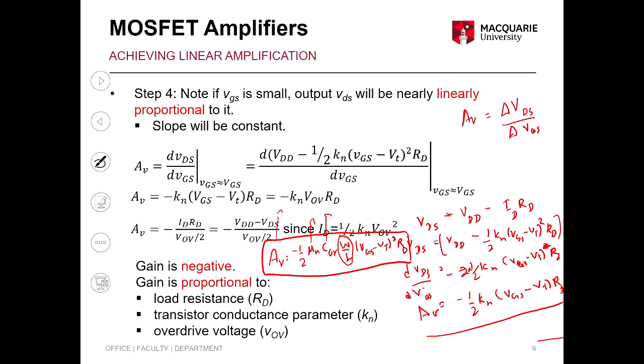As a designer, you should know whether you should double your width. This is a tip for your assessment. When you do your first schematic, let's say you use 2 by 25 initially, then 2 by 25 in the second stage. Then you might say, I'm not having enough gain, so I might have to use a 2 by 50 in the second stage, or 2 by 75. You need to make the decision. You are intuitively using these things, but this puts a perspective on what this equation tells you. The only outcome I want from here is that you understand what this equation tells you.